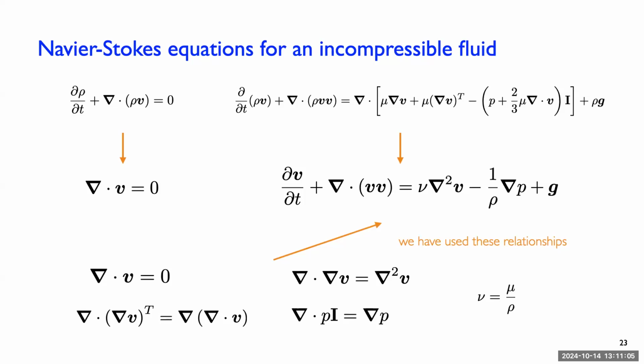So this term here, we have a divergence of a viscosity times the gradient transposed. With just some maths manipulations, we can rewrite that as the gradient of a divergence of velocity. And once again, this divergence of velocity is zero, so that means this term drops out. And then as shorthand, a divergence of a gradient is just written as a gradient squared, or a Laplacian operator, it's called. So that's where this term comes from here. This one dropped out, this one dropped out, so now we're just left with pressure.